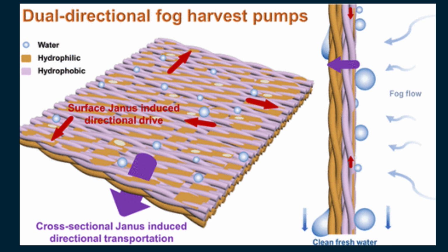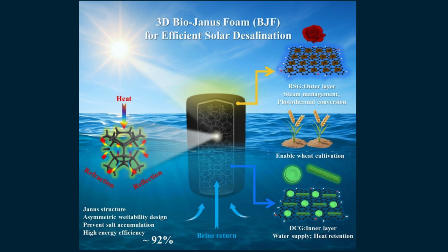Engineering applications of dual Janus foams. Personal thermal management. Janus foams can be integrated into reversible textiles capable of providing approximately 9 degrees Celsius cooling in warm conditions and about 11 degrees Celsius heating in cold environments simply by flipping the material. Energy-efficient buildings. Applied to roofs or walls, these materials regulate solar absorption and radiative cooling to improve indoor thermal comfort and reduce energy consumption. Aerospace and electronics. Their lightweight structure, low thermal conductivity, as low as 0.032 W/mK, and EMI shielding capability make them suitable for protecting sensitive electronic systems in extreme environments.